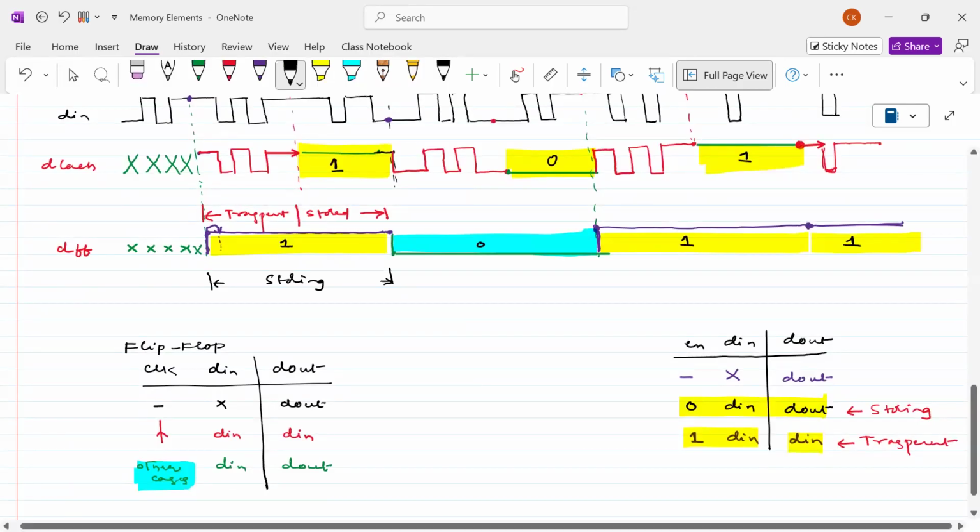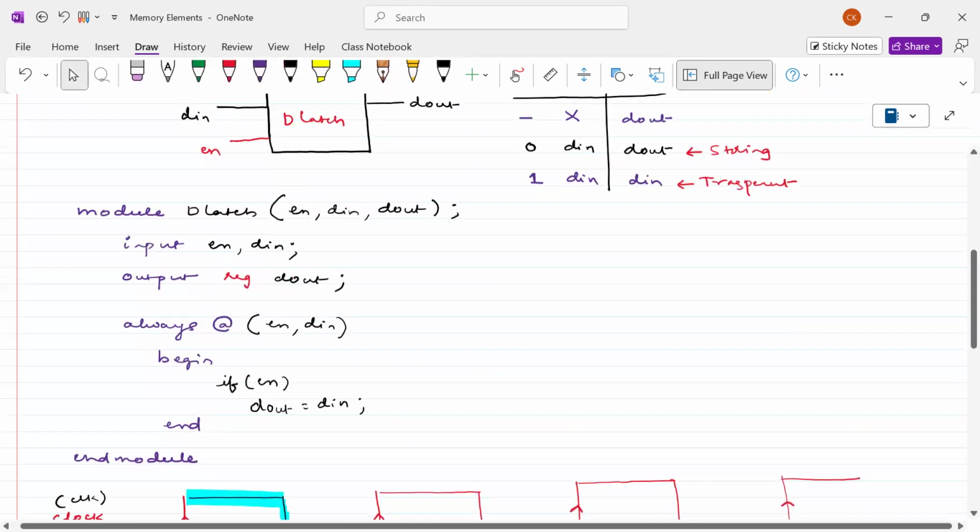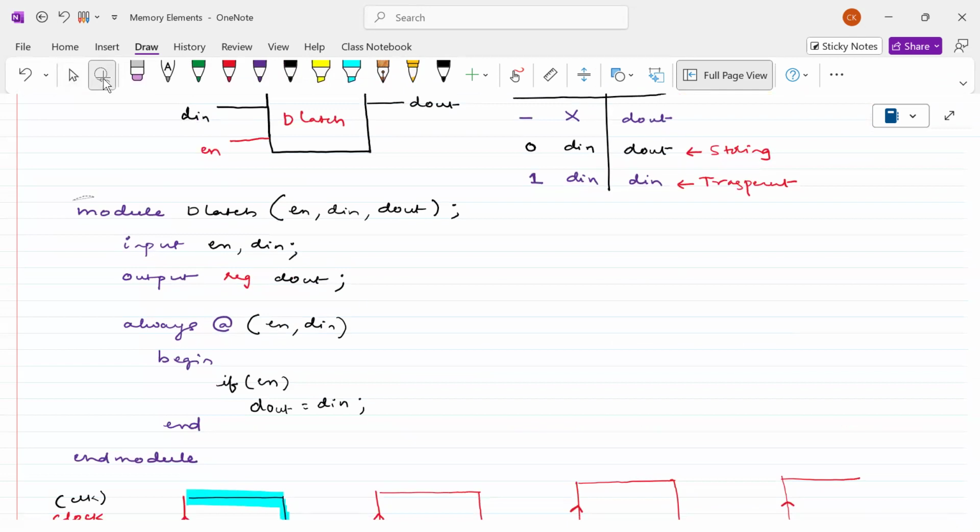But realizing this D flip-flop by using gates is actually complicated. Therefore, we don't want to use data flow modeling or other cases. Equations are a little bit difficult, and the gate-level circuit is also difficult. Therefore, better we go for input-output behavior, and Verilog has given a provision to write Verilog code by looking at the input-output behavior. So let us write the Verilog program for this. Let me take the same program and modify it according to the logic that I have shown.